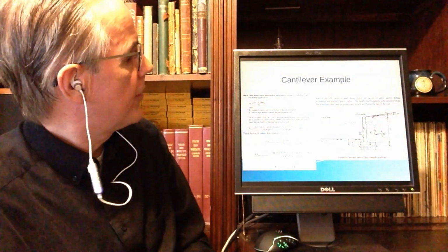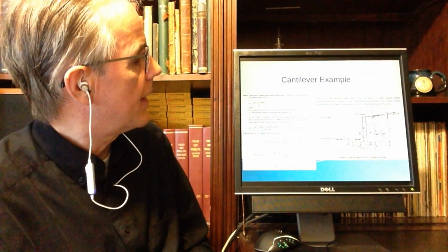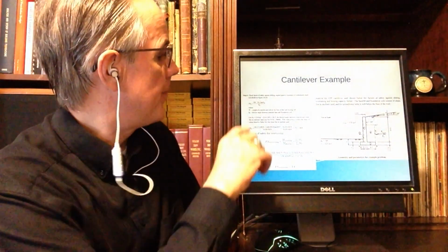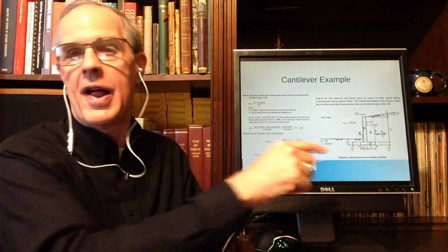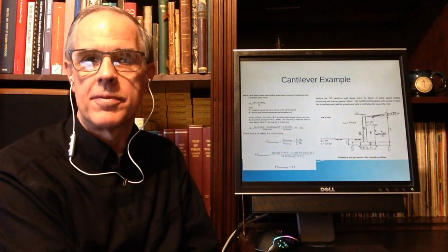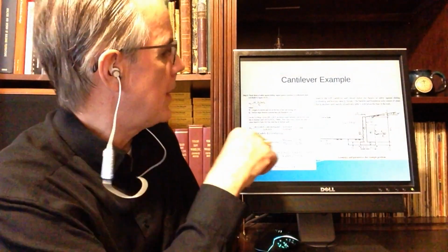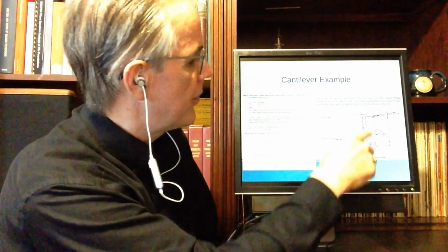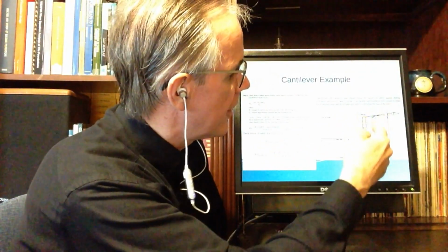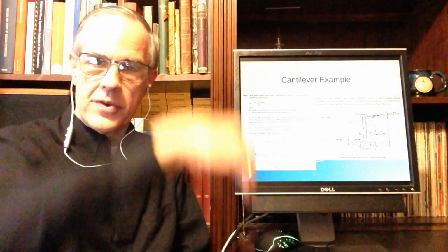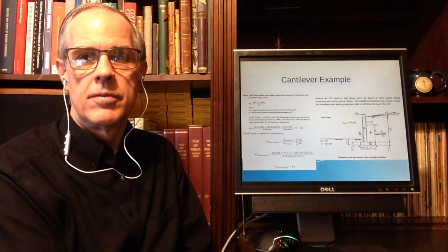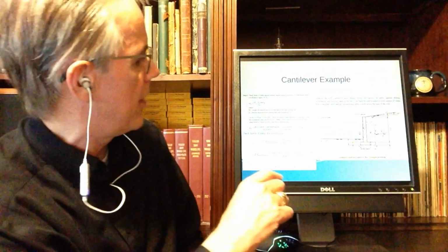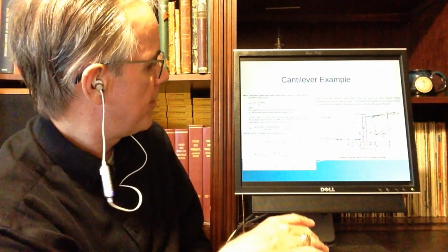Next step, check the factor of safety against sliding. Neglect the passive resistance of embedment, which I told you to do earlier. This is straight up block-on-horizontal-surface statics. The forces this way are all these weights, plus the vertical force along this surface. Those are the two vertical forces acting down, times the tangent of the friction angle here, and this is where you can trip up.